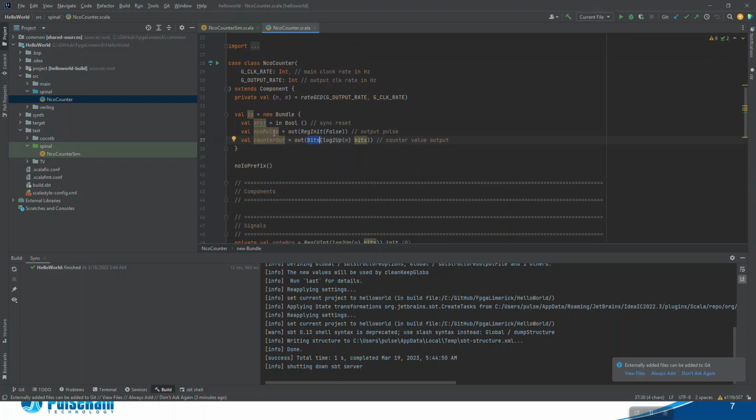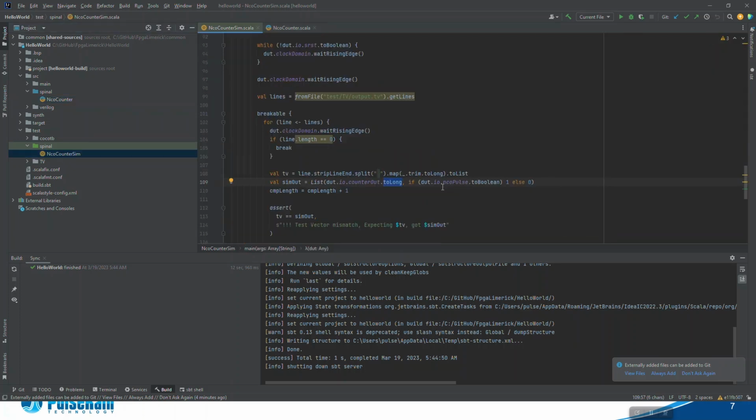Also for this NCO port, it is a Reg Init False. Actually, it's a Boolean, and by default it's False. You probably notice that False in SpinalHDL starts with a capital letter, but in Scala the Boolean has a different type, spelled Boolean. That's why we have to convert this Bool in SpinalHDL into Boolean.